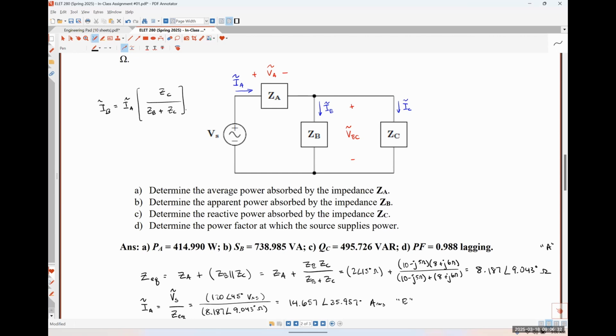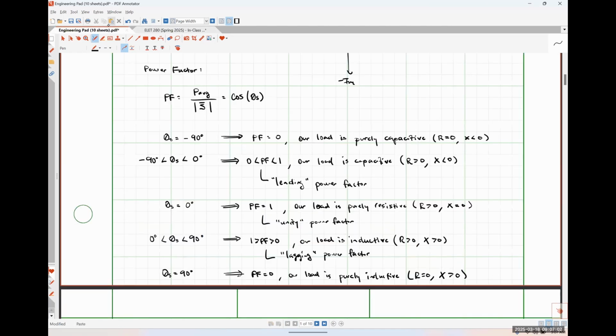This mathematical equation, where you effectively take the current, in the numerator you put the element you're not interested in, only works when you have exactly two parallel paths. But we can have more than two parallel paths. So what I'd like to do really quickly here, as kind of a tangent, is show you how current division can work for an infinite number of parallel paths so that you'll have a more general purpose expression for current division, okay? So we'll do this over here in the notes section.